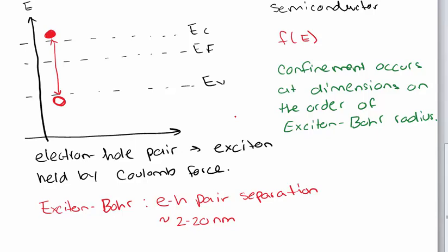But now let's talk about what happens after this electron jumps up to the conduction band. Does it stay there? Well, no. That electron will eventually lose its energy and come back into the valence band. And the way it loses that energy is by emitting a photon. And the energy of that photon is the transition energy between the conduction band and the valence band. So the wavelength of that photon is determined by the energy of the band gap.